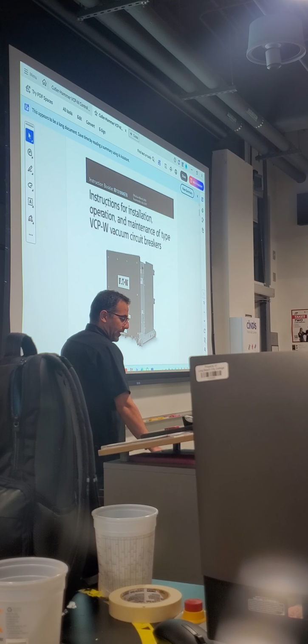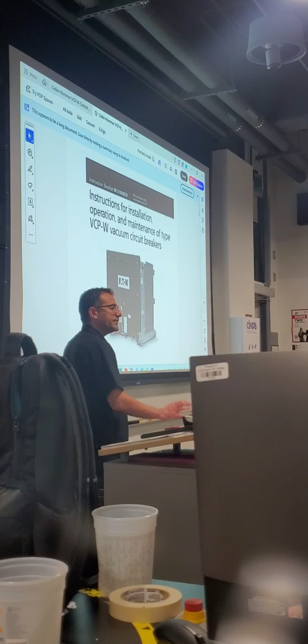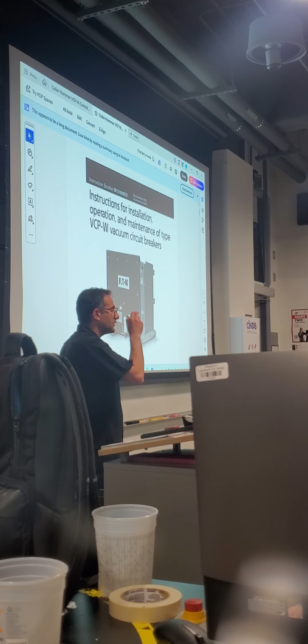We're going to be working on the control circuit of the circuit breaker. You did the Megger and DLRO on this breaker, right? And you're going to do the high pot on this next week, because that's the only medium voltage breaker we have in this class.